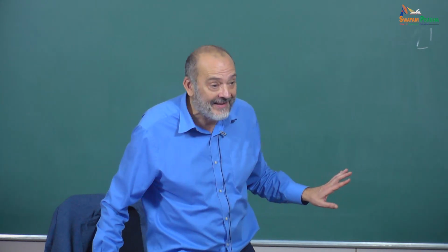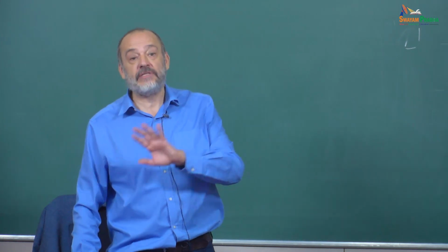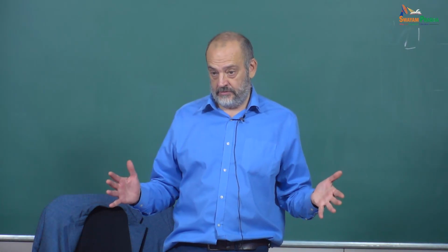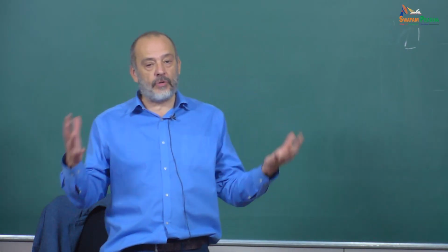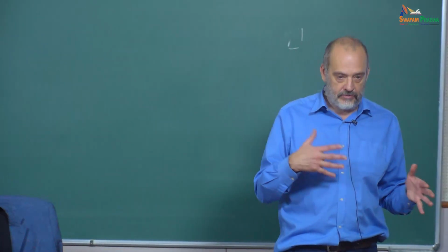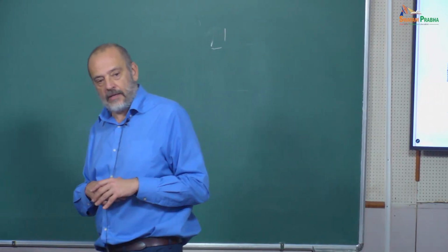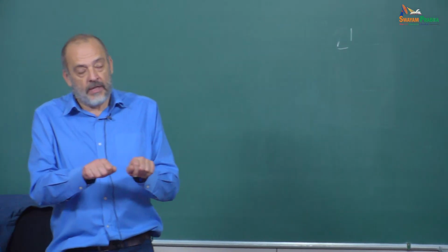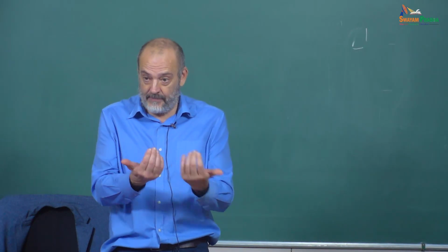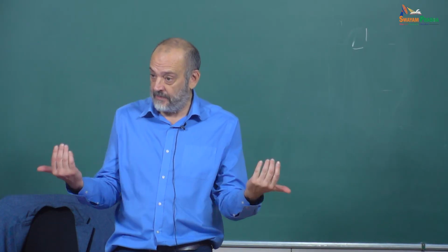And this is for water, and we know water very well. If you consider other fluids, it's worse. The deviation between different models is really huge. So pay attention when you're doing experiments or simulations close to the critical condition to have the right properties, or maybe try a sensitivity analysis to understand what is happening with the different models, because this can be really important.